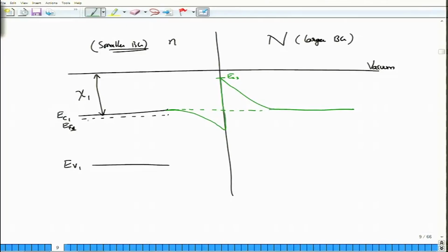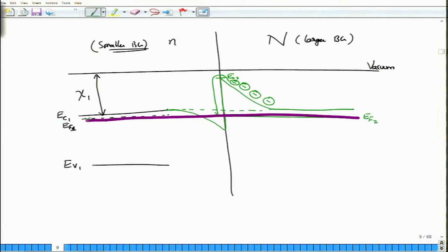What about the Fermi level? Well, we draw the Fermi level here. So, this is my Fermi level overall. As you can clearly see, EF1 and EF2 are the same and they are constant. Now, look at this very interesting thing. The Fermi level is lying above this well. What does it mean? The Fermi level tells you that this is the region where 50% of the probability happens, but because there is a well here, the electrons which have a smaller affinity have actually moved and then fallen into this accumulation region.